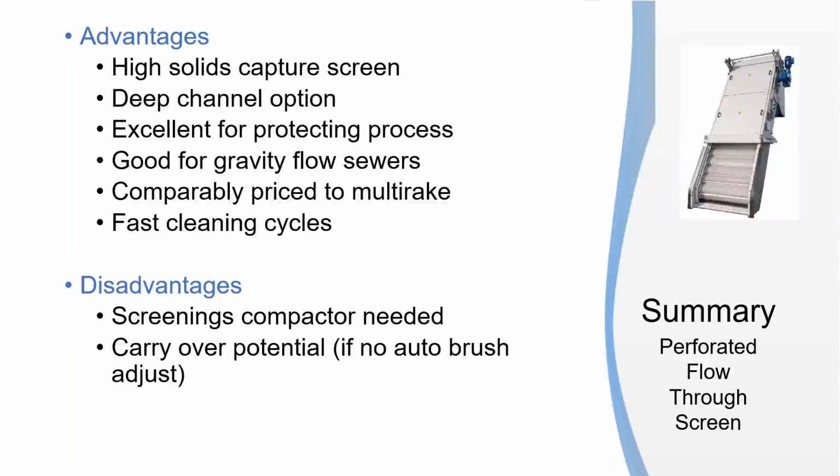Now, a perforated plate screen is the opposite. It has a very high capture rate. It's one of the main advantages it has. It can also fit into a deeper channel. We're not going to do 180 feet deep with it. 50 feet is certainly an option.